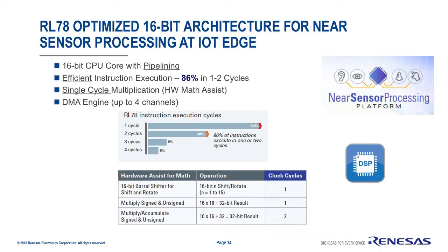This high performance yields a Dhrystone 2.1 benchmark of 1.39 Dhrystone MIPS per megahertz, or about 44.5 Dhrystone MIPS total at 32 MHz operation. Additionally, instruction lengths are in increments of bytes, sizes of 1 to 6 bytes instead of full multiples of 16-bit words, so the fine granularity of instruction length reduces the overall code size.